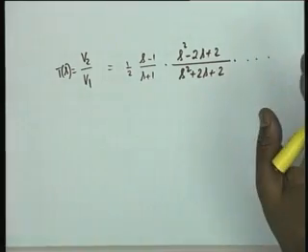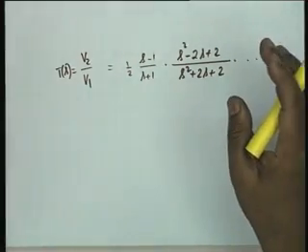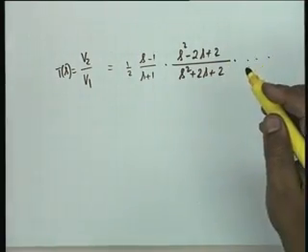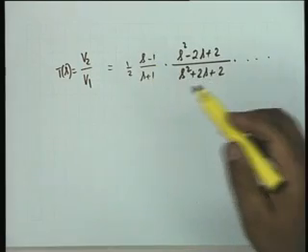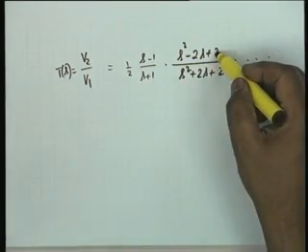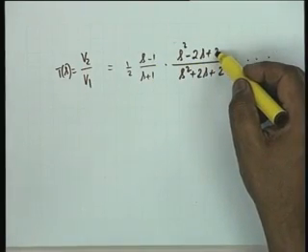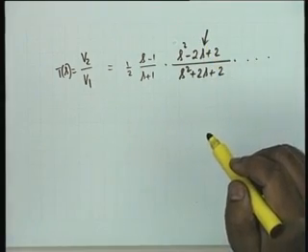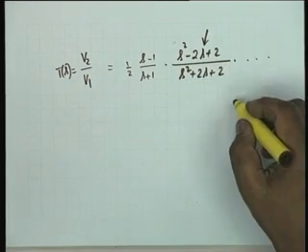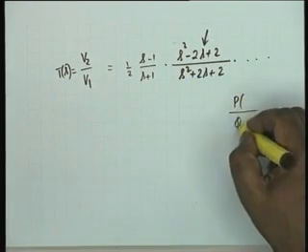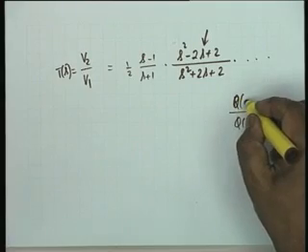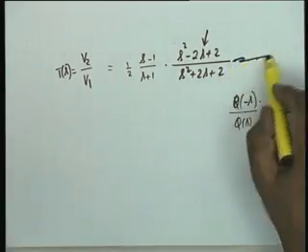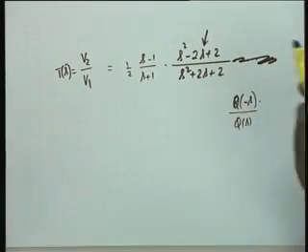It is a very complicated function, but non-minimum. Pardon me? This is non-minimum phase. Yes. How do you know it is non-minimum phase? Because there is a 0 at plus 1. This also gives zeros in the right half plane. And do you realize that this is also an all-pass function? What is an all-pass function? If the denominator is q of s, then the numerator must be q of minus s. That is right. So this is also an all-pass function. Suppose, for example, this is what we wish to realize.